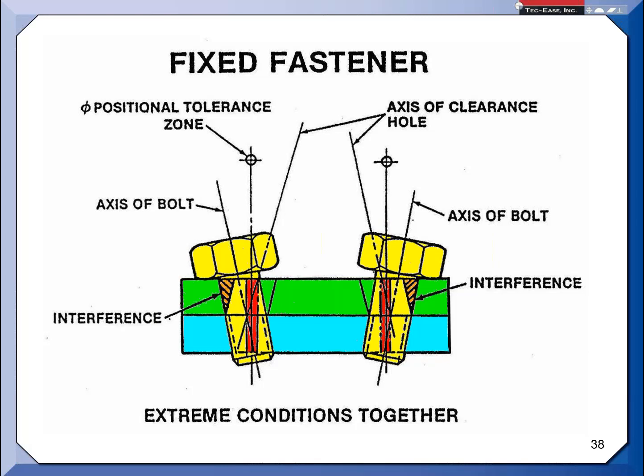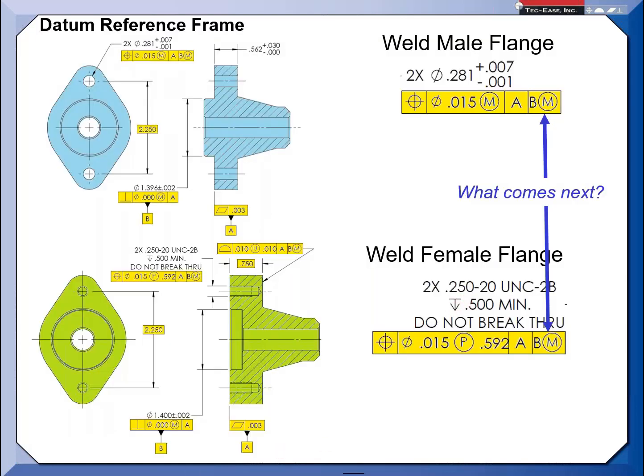Yeah, so when we did this, let me get to the appropriate slide. Notice that I have a circle M here. That's a tolerance modifier because it's in the tolerance part of the feature control frame. The syntax calls this the tolerance modifier or the MMC condition.